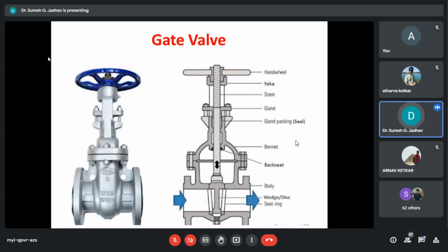So next part is hand wheel and hand wheel nut. At the top there is a hand wheel and hand wheel nut. The hand wheel is affixed to the stem by a threaded hand wheel nut. The arrow pointing the direction to open the valve will be marked with the word open or close. We can rotate these hand wheels and mark them with the word open or close or shut unless the size makes it impracticable. Valve shall be closed by turning the hand wheel in clockwise direction.